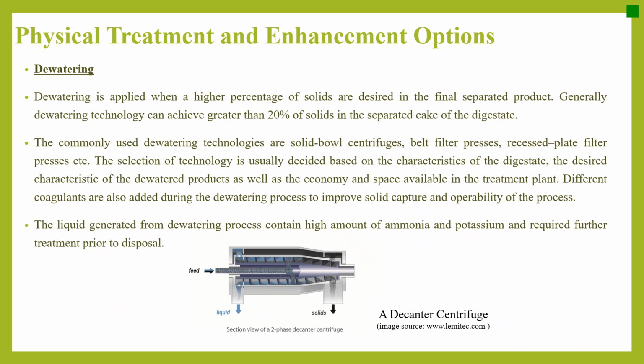Different coagulants are also added during the dewatering process to improve solid capture and operability of the process. The liquid generated from the dewatering process contains a high amount of ammonia and potassium and requires further treatment prior to disposal.